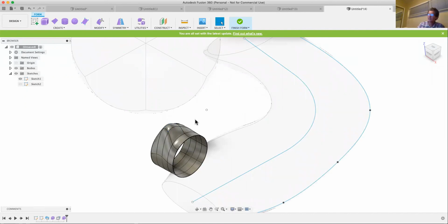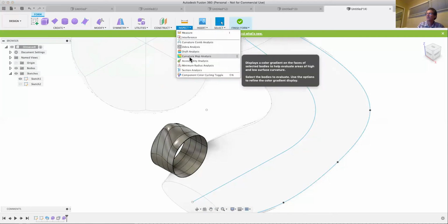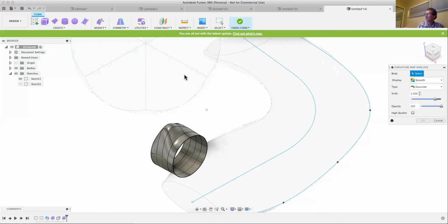And one of the advantages is there's nicely smooth flowing surfaces in here. And when you build things with multiple features in solids modeling, it's hard not to get discontinuities. If you have something that's squarish and you put a fillet on it, it's a discontinuity. You're going from a zero slope to a fixed positive slope rather than a smooth, gradual transition. And that's what some of the analyses, the curvature map analyses and things like that are for.